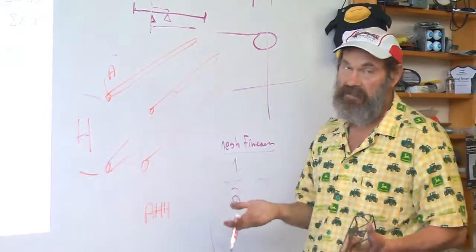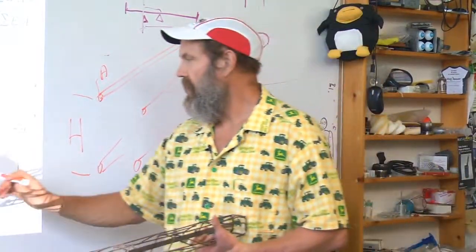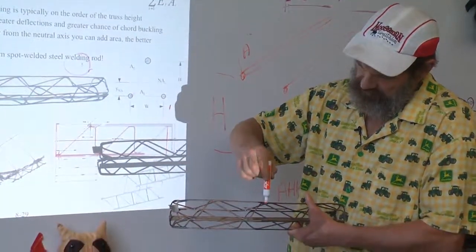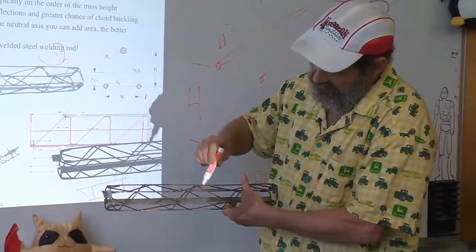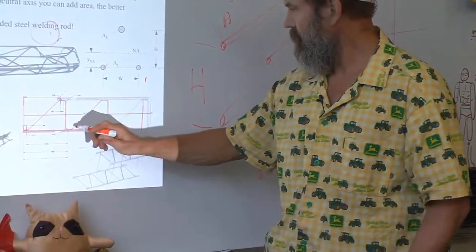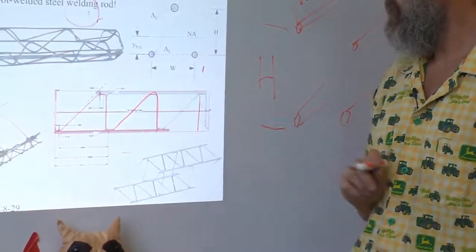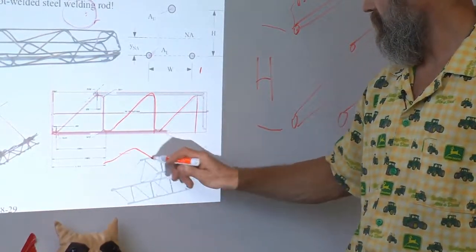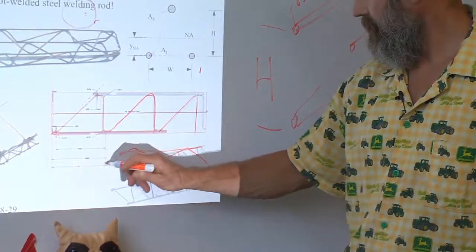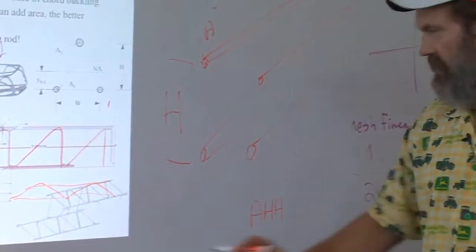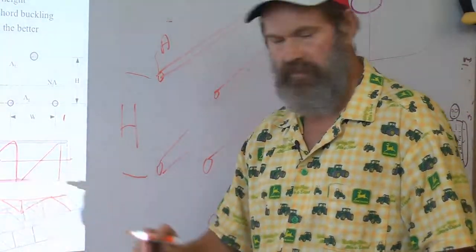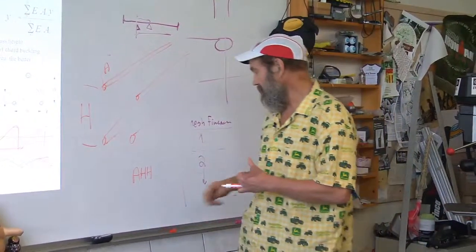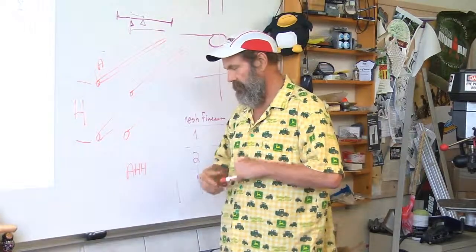Now you've got the detail, because that's what we're getting is finer and finer detail. How do I know how to put these braces? Should the braces be like this triangle, or this kind of triangle? Why are some this way and others this way? Why sometimes do you see a post in the middle? Well, it gets back to the stability question of buckling.